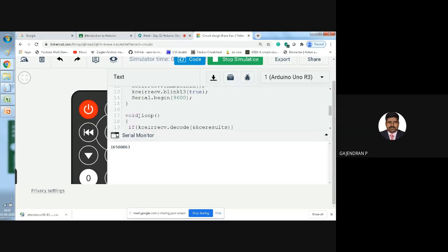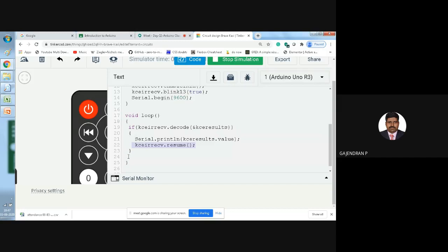See what mistake we made: we made the reset action outside the whole loop. So all the time, whenever it enters the loop, it immediately resets, so it is not given the time to process. That's why, in the loop condition, whenever it receives, I process it, then I reset and come back from the loop.